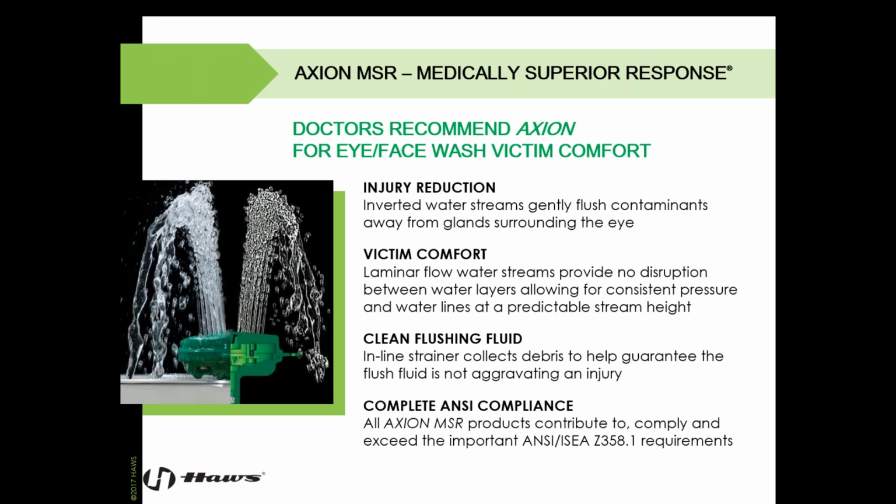We also have flow control within the unit, within the head of our unit. So if there is excessive pressure from the back end, that flow control in the head of the unit is not going to allow the Axion eye face wash to become an eye pressure washer. Clean flushing fluid within the unit, there's an inline strainer. It's going to collect the debris to help guarantee that the flushing fluid is not further aggravating the injury. A part of the weekly inspection is also to clean that out. So you've got double protection, cleaning it out on a weekly basis, and we've got an inline strainer.